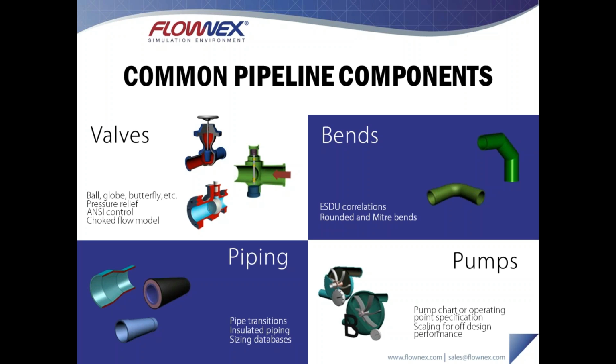Our bend components are for both rounded bends as well as mitre bends. They employ ESDU correlations, and the bends themselves also have results for the forces or the reaction forces that are required to support these bends.